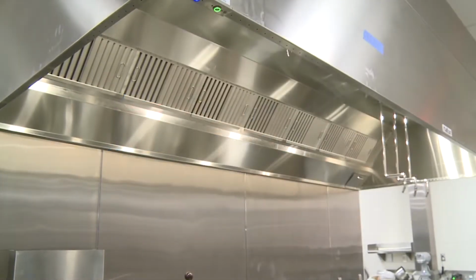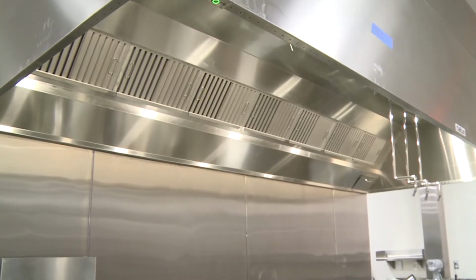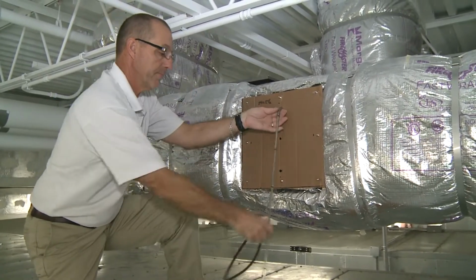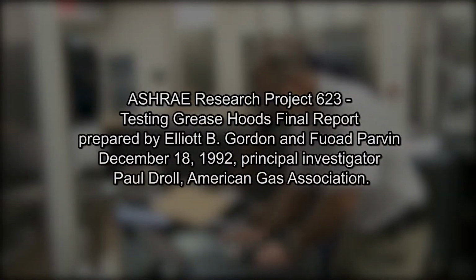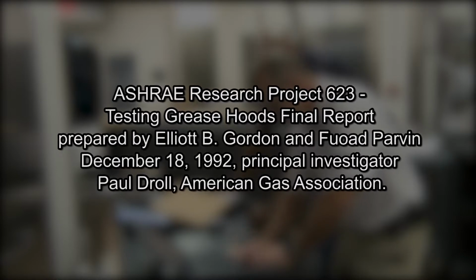A method was developed to test grease hoods because the welded ductwork is encapsulated by 2-hour firewall. Fire codes would not allow the pitot tube traverses. ASHRAE Research Project 623, Testing Grease Hoods, final report prepared by Elliot B.